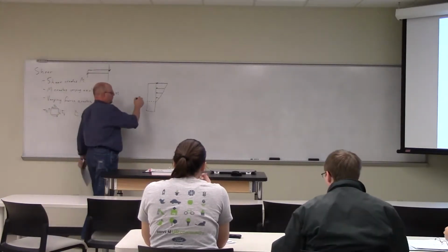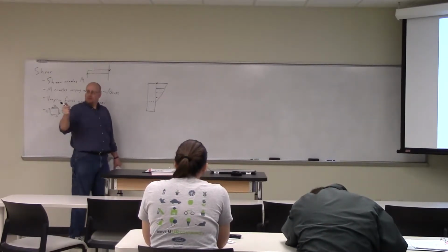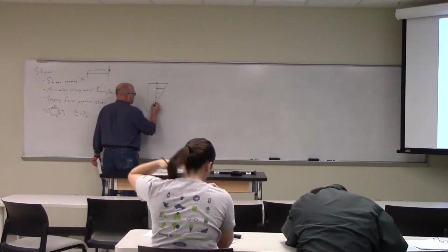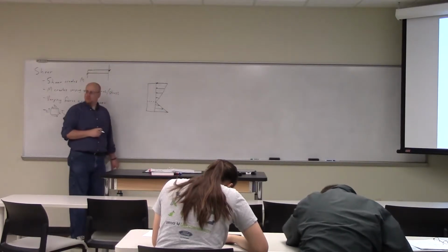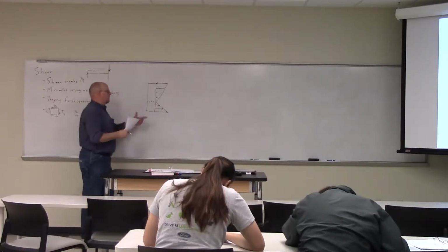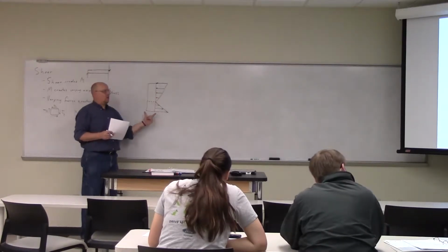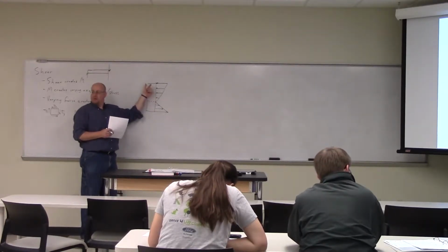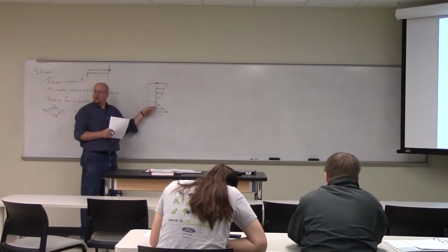So let's consider this drawing. Now, I've drawn the top half, the compressive half, but somebody over here said it was tensile on the bottom. So there's a stress on the bottom that is tensile. And given the fact that the bottom is fatter, if you look in the third dimension, into the plane, T is a bigger value for the bottom than it is for the top. That's how the sum of these forces and the sum of these forces balance one another.